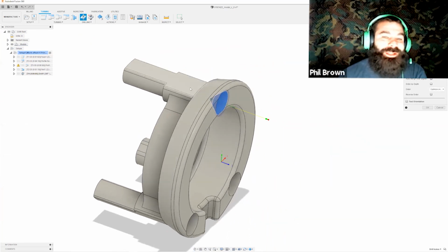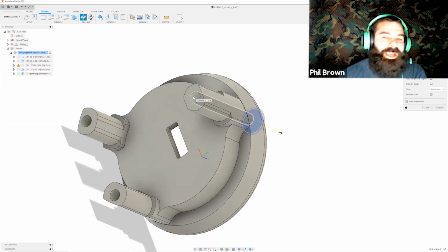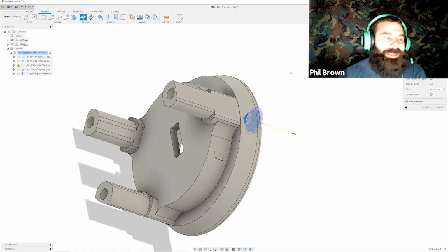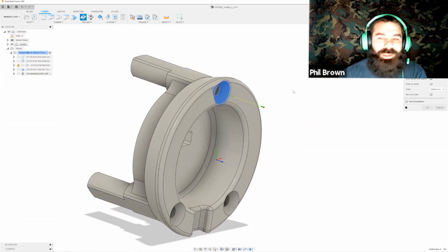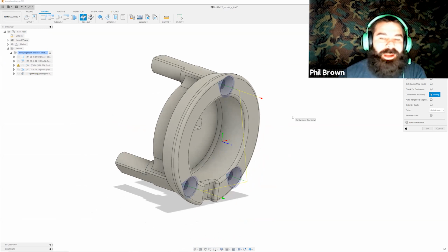In part 1, you'll actually notice on this part, Jason, although he is a great designer, gave me a very nasty groove along this face and opened up these holes here. And with that, there's no way I'm going to hang a tool 20 times out deep and expect a good surface finish. So with that, we're going to go ahead and move a little further here. I'm going to say select the same size holes. And as you can see, it automatically picked up all 3 of those holes for me.